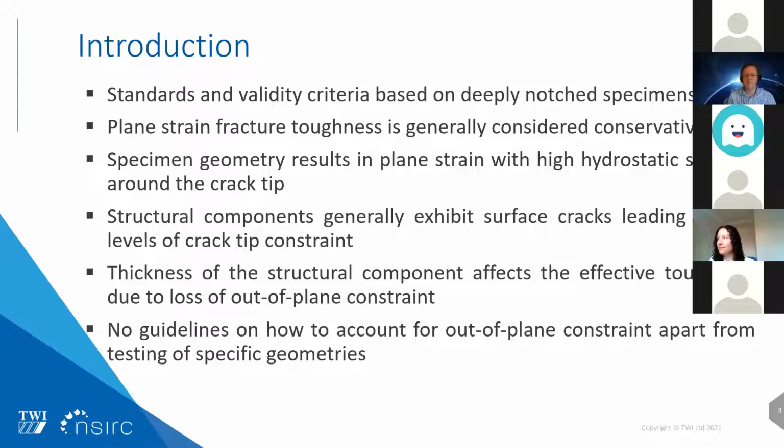However, engineering structures such as oil and gas pipelines are predominantly loaded in tension and contain shallow cracks, which exhibit low levels of crack tip constraint, leading to an increase in the fracture toughness.